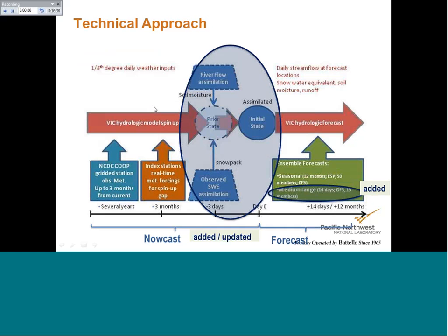And then one last thing is, because we now look at shorter timescale, the improvement that we can see from data assimilation is going to pick up just a couple days after the assimilation, and that time is the time of concentration of the basin. So in order to have improved forecast from day 0, we do perform the assimilation a couple days before the actual forecast.